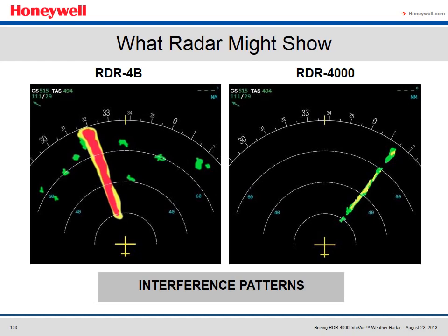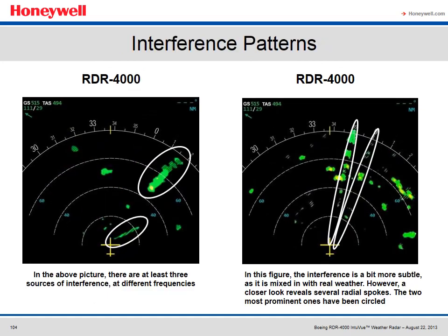They can look the same on the RDR4000, or they can also look a little different because they are collected over multiple sweeps, motion compensated in the buffer, and separated into flight path and secondary returns. The interference will remain on the display until the source is gone and the motion compensation of the buffer data moves it behind the aircraft.